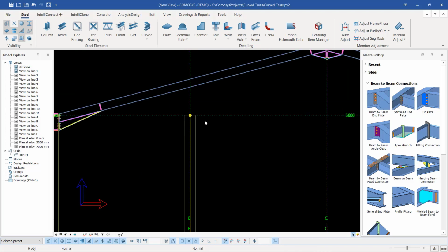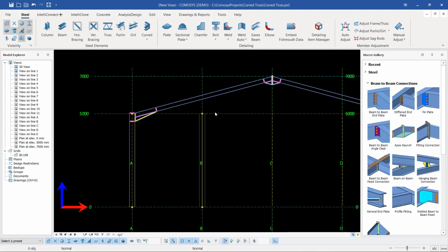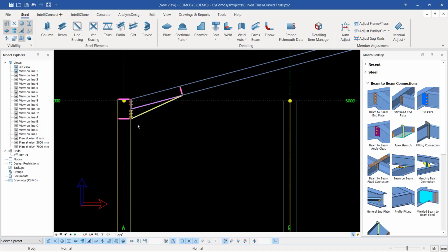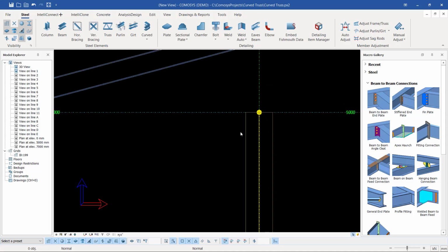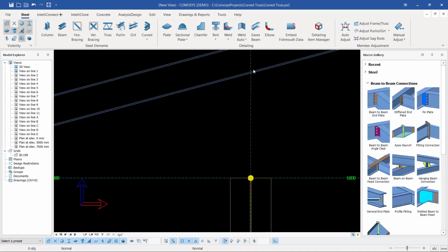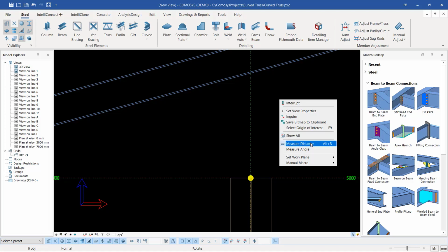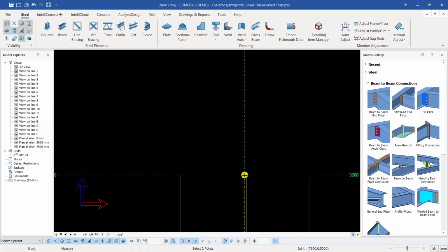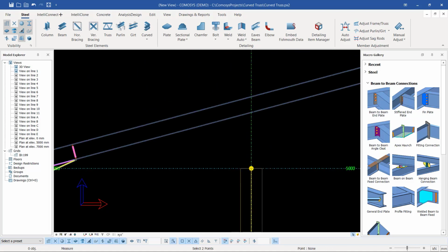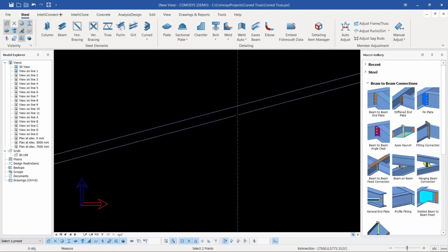By default, we have a default height of the columns. It will be similar to this one. So to extend this, first of all, you have to check the distance remaining, then you go and add on the default height of the column. Now I'll right click and come to measure, then I'll snap on top here, then move all the way to this bottom end here and snap right there.